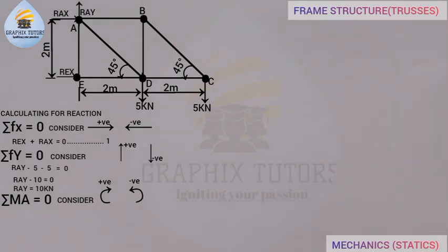For instance, if I take the force at point D acting downward, the moment will be going towards point A in this manner, going in the direction of point A, right? And when we look at that, that is clockwise. From B to D, this force here is perpendicular to this distance here. Are we good now? This force at point D is perpendicular to this distance here. So it will be going towards point A. So we have 2, that is 5 times 2, right?